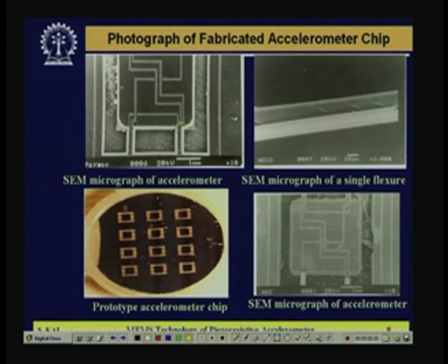So this is basically the flexure. Now this corner you have seen that it has been etched, and ultimately it is rounded here. Similarly here also rounded. But if we need the perfect square structure, then what is normally done on the mask side, you have to make a corner compensation structure, something like that. So if you make that, it will attack from this side, from this side, that side. So ultimately it may end up in a complete square.